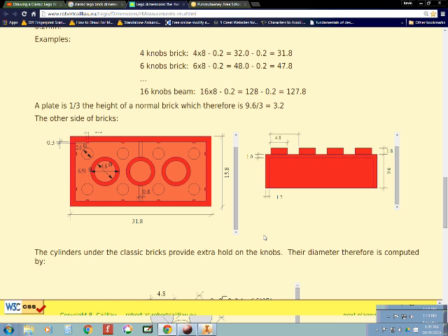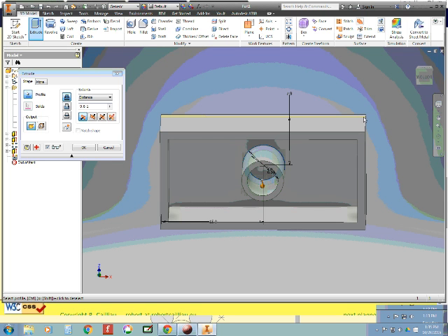And let's take a look at that. How do you know that's what they are? Well, you know they're extruded towards you because you can see if they were extruded away, there'd be other hidden lines in here. If they didn't come the whole way to this surface, there would be hidden lines across here showing where they stopped. So you kind of have to assume that this extrusion comes the whole way out from where we started on this surface, flush or even with this surface. And that's that same distance, that 9.6 for that whole height, minus that 0.1. I'm sorry, minus 1, not 0.1.